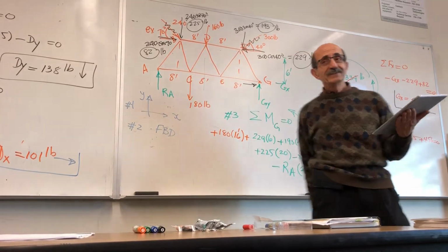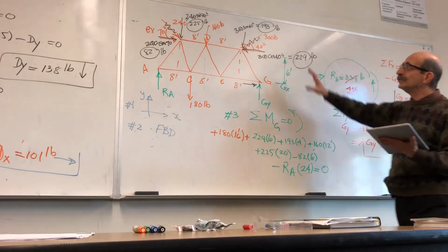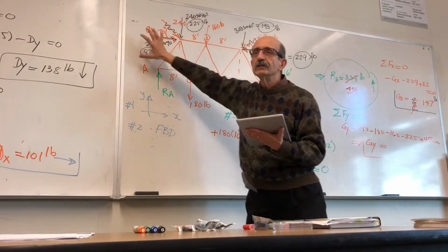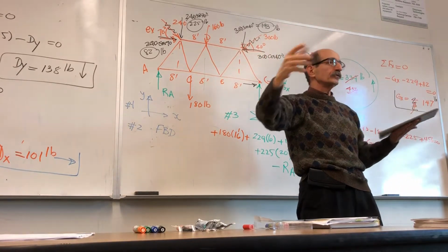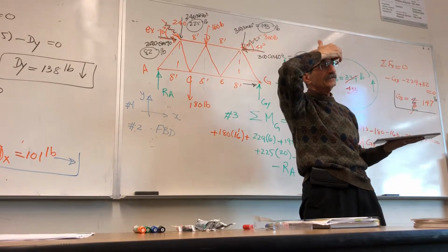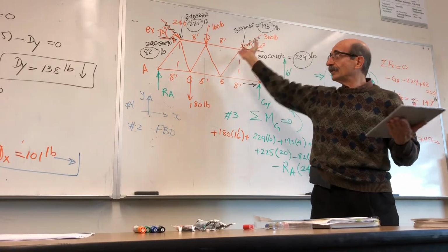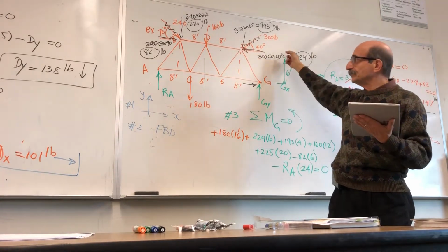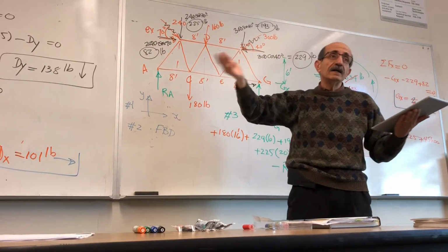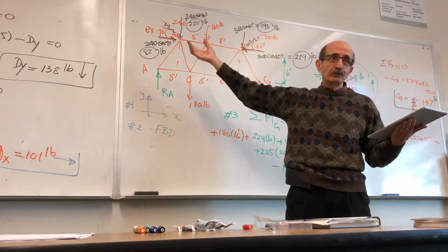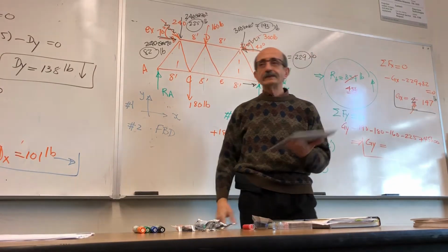It's only asking you to replace all these applied forces with a single force. And you know how to do it, right? Replace all of them with a resultant, put it, say, at point A, and the summation of the moments of those forces at point A, put it there.